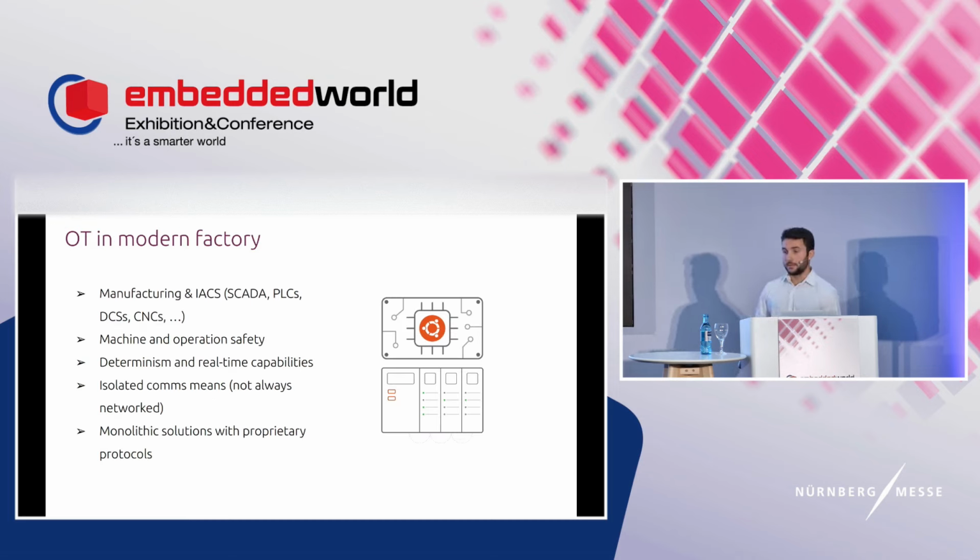Starting with OT in manufacturing. Operational technology describes the hardware and the software systems that tend to execute and control processes on the shop floor. So here we can think of the production lines, the manufacturing systems, all kinds of mostly legacy machinery. And this legacy infrastructure tends to pose a barrier to data sharing between devices, but also to two-way communication between devices. The operational technology domain is characterized by a lack of uniformity.